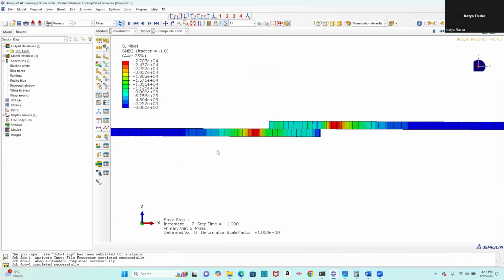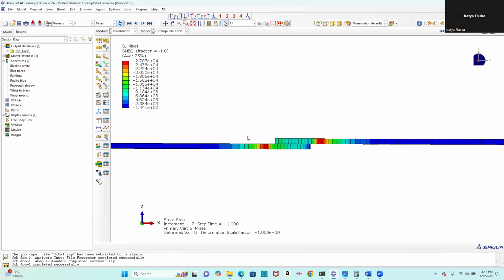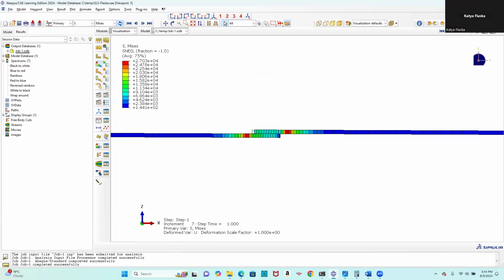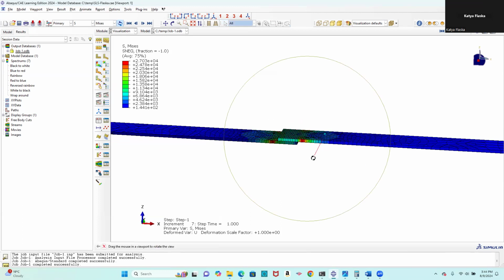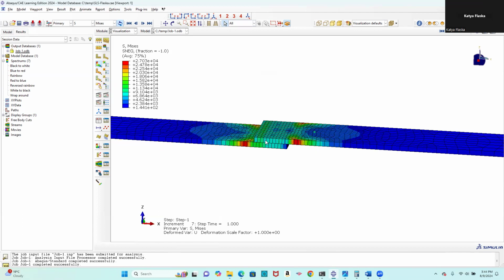Theoretically, if you were going into a non-linear FEA, you could evaluate, and you'd like to evaluate this coupon being pulled far enough that it fails the adhesive between the 2 layers and the coupons are no longer attached. But because this is a linear finite element model, we're really just looking at the stress here to understand how the laminate or the metallic coupons are affected.